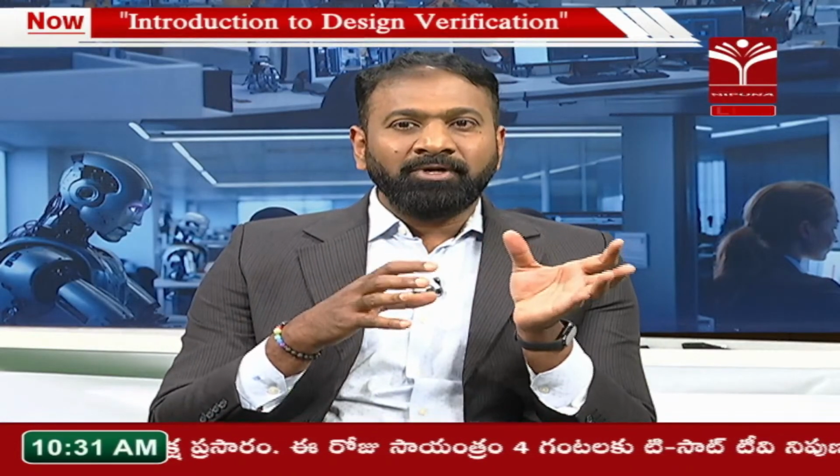Thank you. So, what we are going to do is we have input and output, and both the inputs and outputs are going to be captured at a scoreboard component. Do not worry about understanding the scoreboard in depth, but it is a component where you are trying to compare the inputs and outputs. If my input and output are matching, I am saying that yes, this specific functionality is met. And how am I going to monitor my overall progress? There will be a component called the coverage component. So, this constitutes an entire SystemVerilog test bench environment.